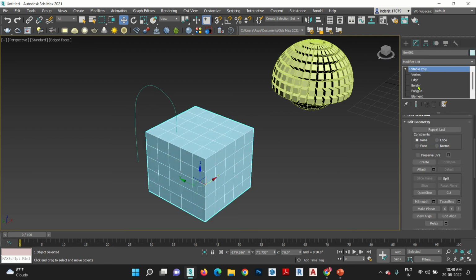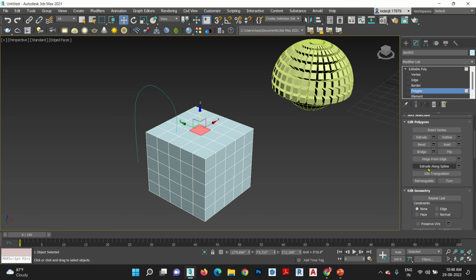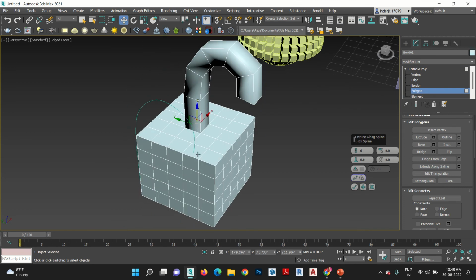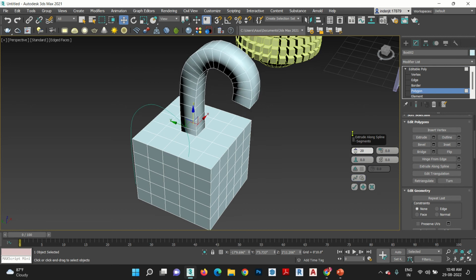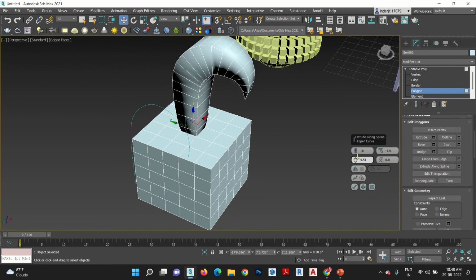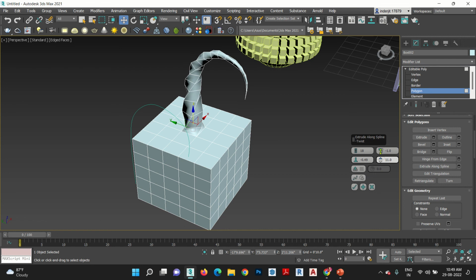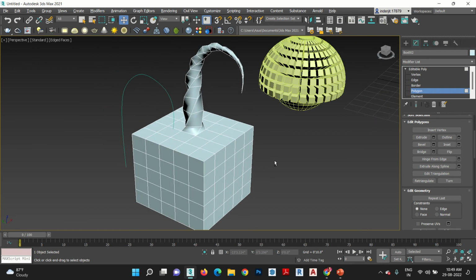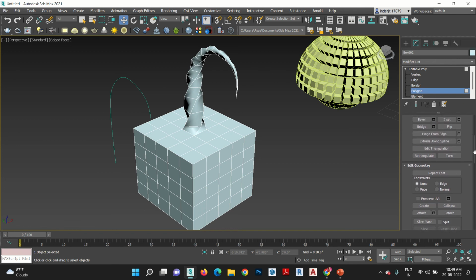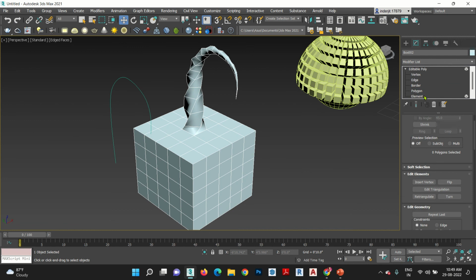Now go here, select polygon, select any of your polygons, extrude along spline. Click here, select your spline. Which spline? This is my spline. See, my polygon is extruded exactly according to this spline shape. Now you have to edit it. You can increase or decrease the segments. This is taper shape. This is twist. Right. Rest of the things. Now come to element.